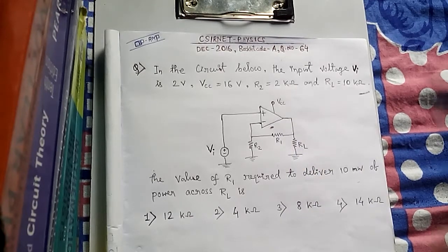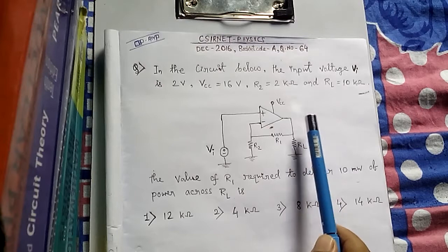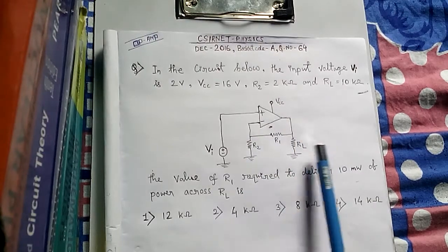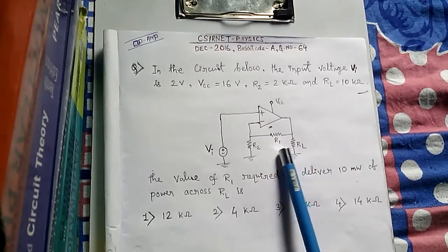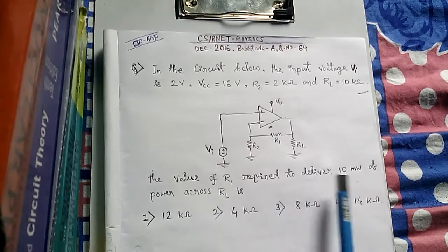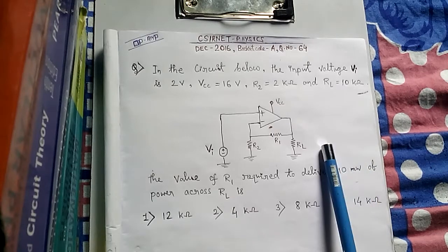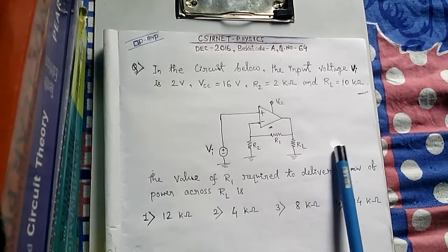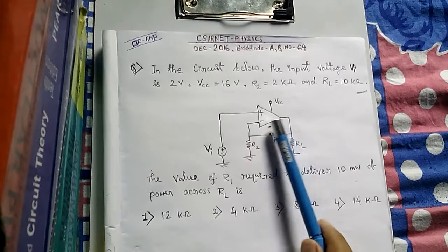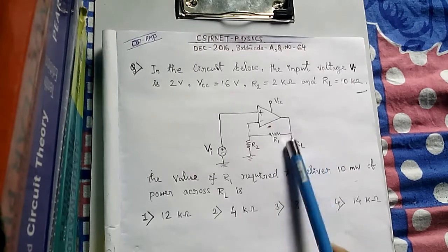This is the concept. And how can we directly know the output not using this circuit? Because this condition of power dissipation, or power consumption, has been given. Using this we know power equals V into I. Using this we can find the V, and this V is V output, because this is the voltage that is dropping across this RL.